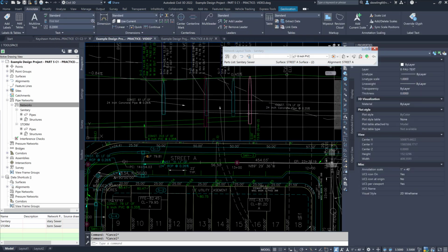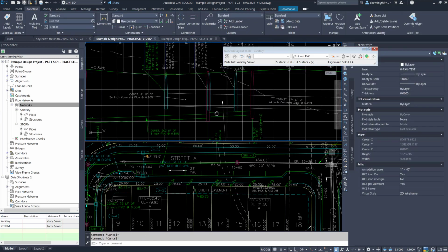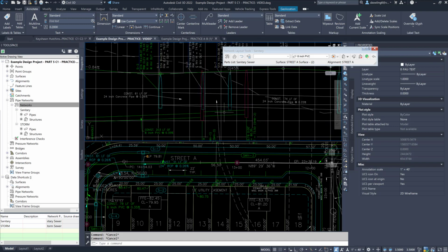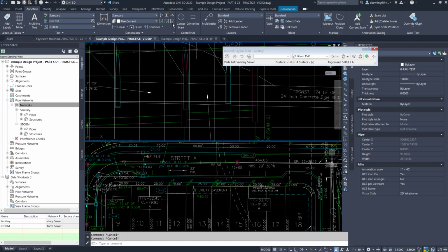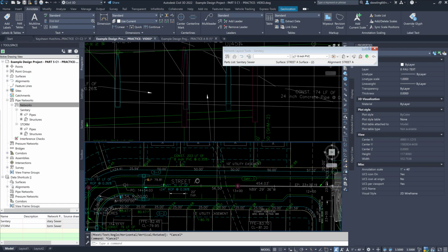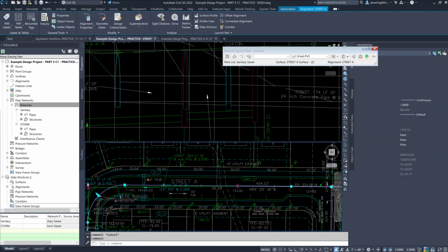But now we've got our sewer much further separation from the storm. So if I measured this, I'm going to do linear, from this bottom to this top is 7.35, which is actually 0.735. So it's greater than 1/2 foot, and that's all you need per the county or per the city standards and FDEP standards.